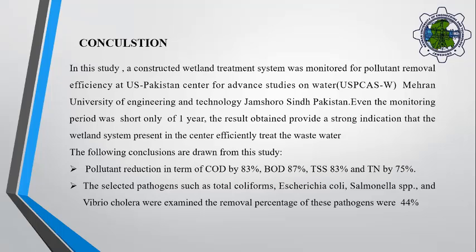The results obtained provide a strong indication that the wetland system present in the center efficiently treats the wastewater. The following conclusions I draw from this study: pollutant reduction in terms of COD by 83%, BOD 87%, TSS 83%, and TN by 75%. The selected pathogens such as total coliform, Escherichia coli, Salmonella, and Vibrio cholerae were examined, and the removal percent of these pathogens is 44%.